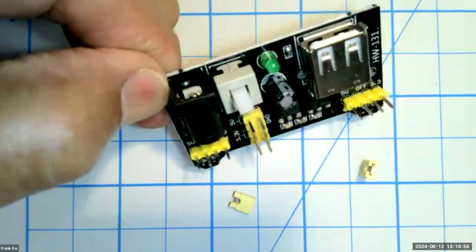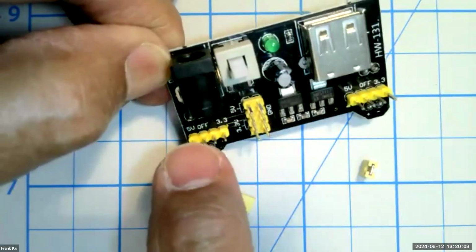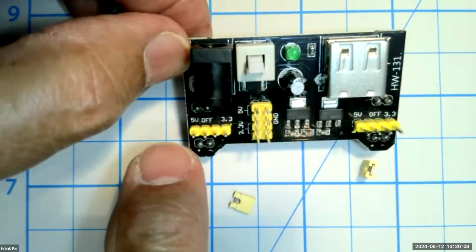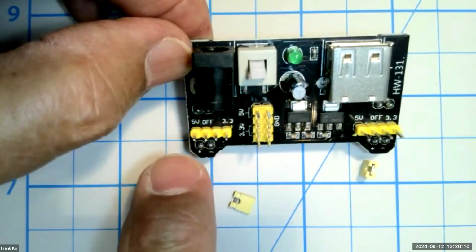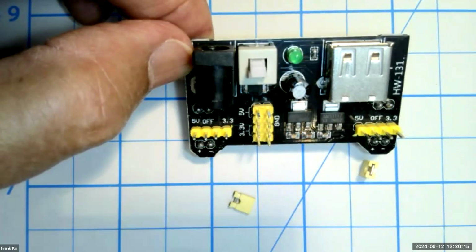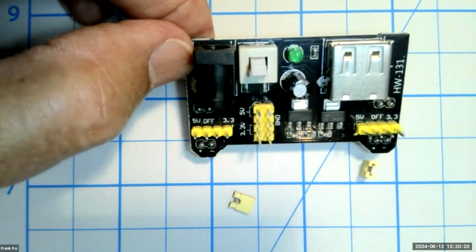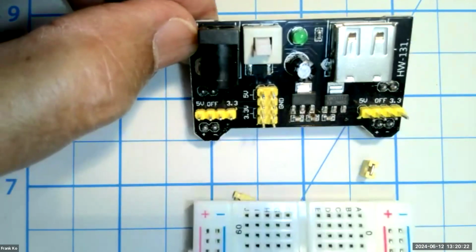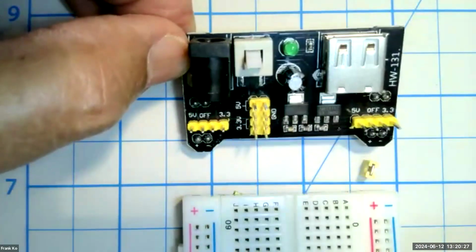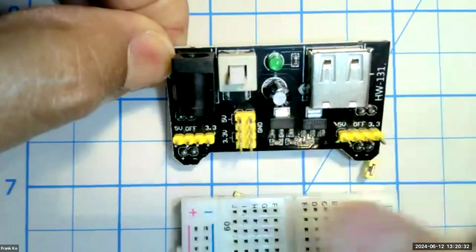And as we've indicated, you want to set this up in such a way that on the right side of the board, as shown in the illustration, we want to connect between the far left pin and the pin next to it so that we are supplying 5 volts on this side of the power supply to the rails of your breadboard. And the power rails of the breadboard will be corresponding to, say, something that looks like this. So the +5 will be connected to the red rail. The off, which is the ground part of the power supply, will be connected to the blue rail.